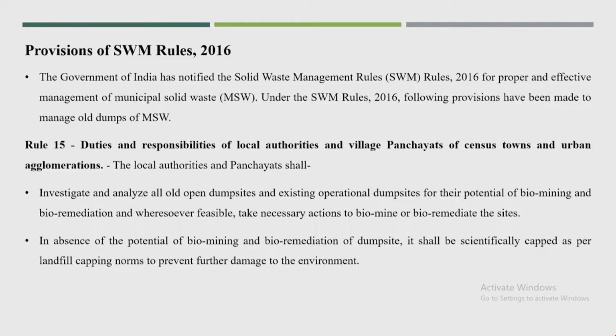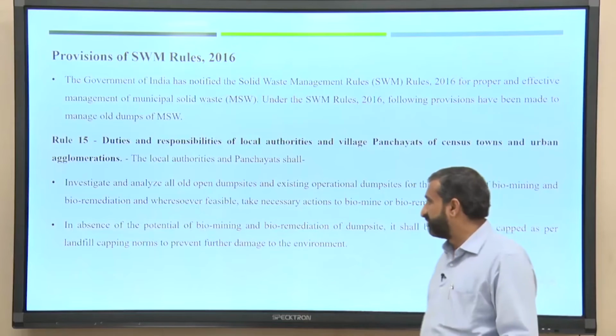In the absence of potential for biomining and bioremediation of a dump site, it shall be scientifically capped as per the landfill capping norms to prevent further damage to the environment. So, it has been explained that if the waste does not have potential for biomining or bioremediation, we need proper scientific capping, not just filling with soil on top of the waste material.